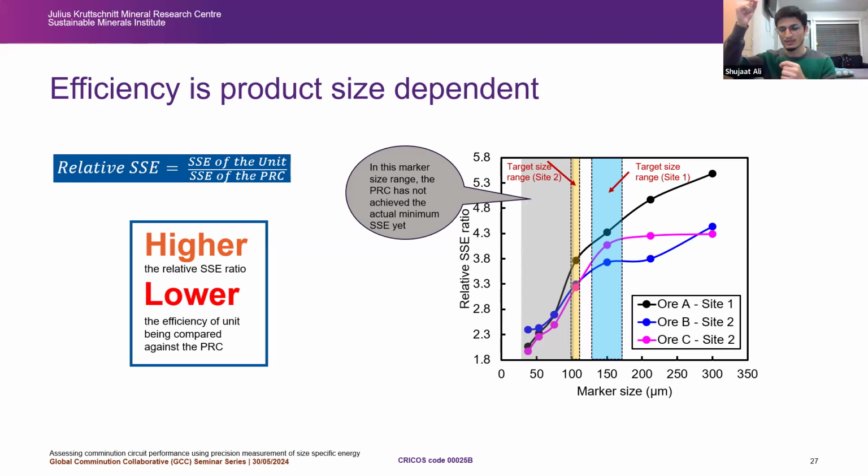I broke a population of particles, I had the energy from short impact load cells, and I did a sizing distribution. Then I started applying different reduction ratios on the same feed type, on the same particle size in my precision rolls crusher. I moved back and forth. And 0.8 was the reduction ratio where I came to a match or close match with short impact load cell progeny, and also with the energy. Which is why I chose that, and I kept it consistent all across.